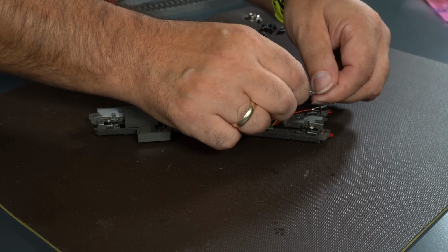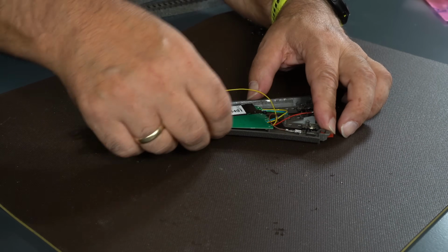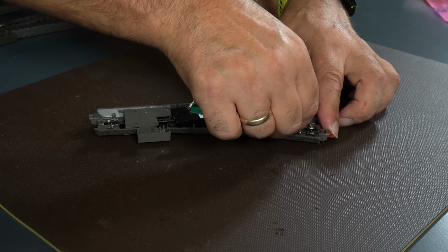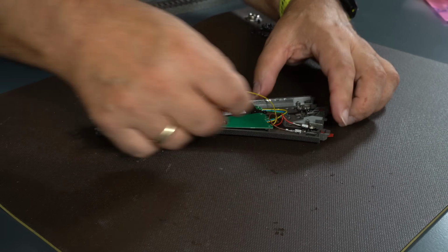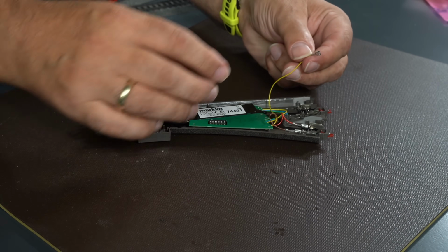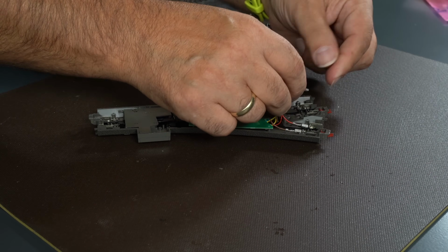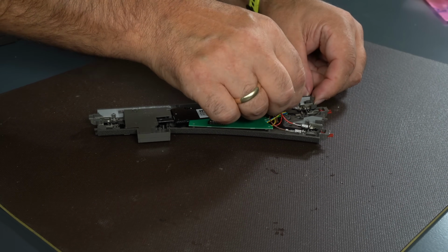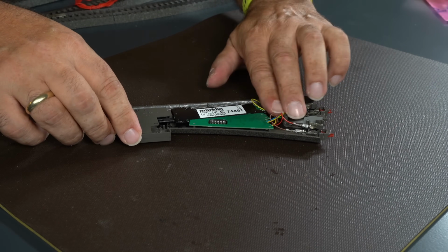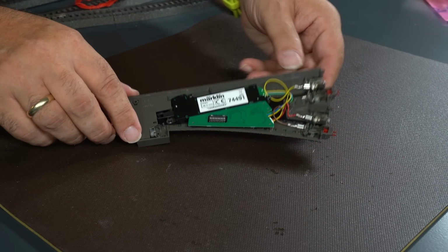Now the decoder still has this yellow wire, which is an auxiliary supply, and that goes on the opposite side, again to track power, so to the shorter tongue, making sure that all wires are routed neatly and do not interfere with moving parts. And with that, the turnout is ready for operation once we've neatly arranged the cables, checked all connections, and ensured that everything is in its proper place and securely fastened. This careful preparation helps to guarantee reliable and trouble-free operation of the turnout system in the long run.